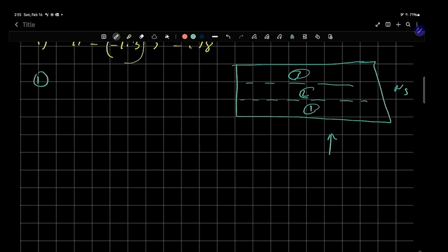Section 1 is basically from the edge of the roof, from 0, that's 2H divided by 2. Our H is 63.5, divided by 2, and that's 31.75, I believe, our first section.